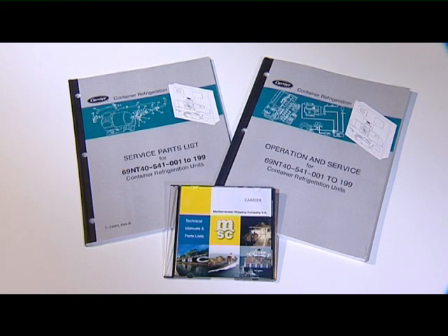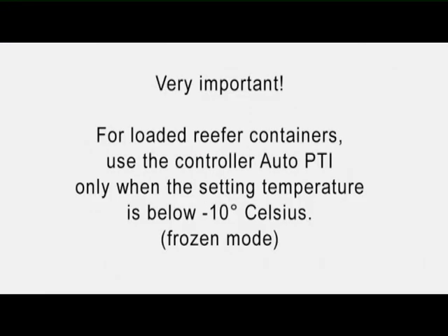All the pre-trip test code numbers with title and description can be found in the Carrier Service Operation Manual supplied to the vessel. For loaded reefer containers, use the Controller Auto PTI only when the setting temperature is below -10 degrees Celsius, frozen mode.